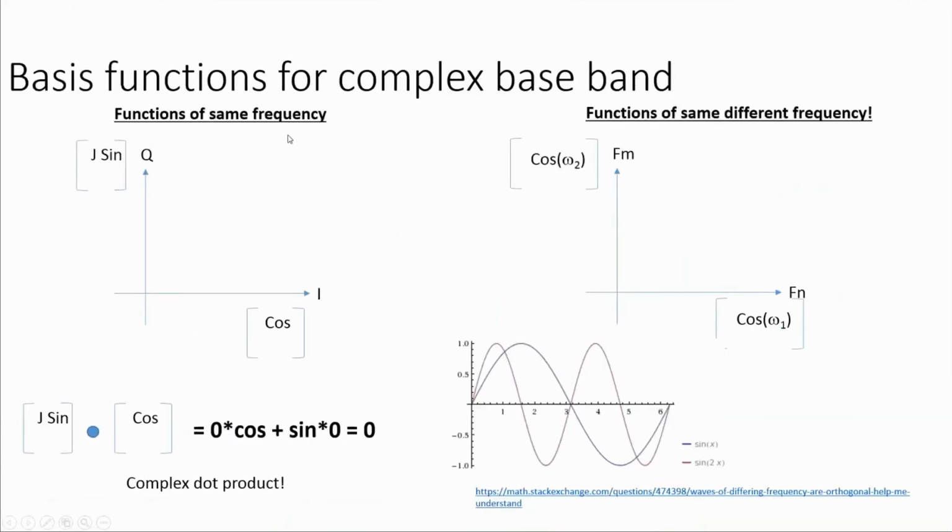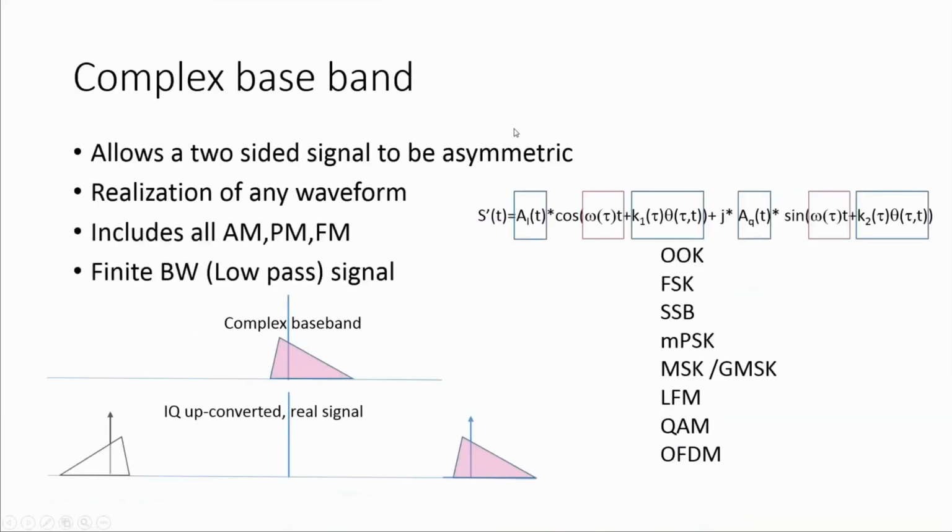Okay, I did that. So just to review complex baseband, we can have any signal be asymmetric. We can have nothing on the negative spectrum. We can have something on both. So that when we upconvert, that relationship is preserved. And that's what a single sideband is. But when you upconvert this by a real signal, the negative frequency does come back, because when you multiply this by a two-sided signal, these two arrows, you get this back. But you can't observe this in a radio system. It's present so that this is now symmetric around 0. But the part that we observe is this piece.